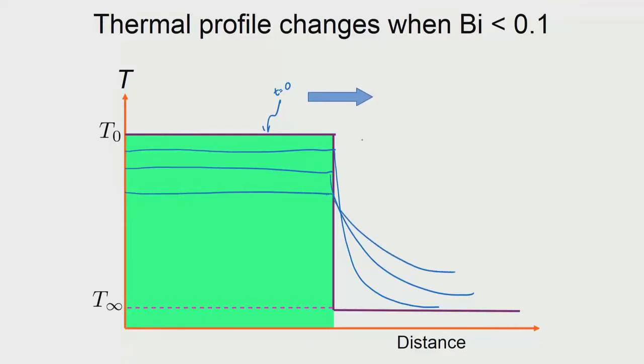So, which means that inside the bulk the temperature is dropping, T is dropping, and outside the drop in temperature is then matched with the heat that is lost, and that Q is of course given by h into T, which is the temperature inside, which is same as the surface, minus T infinity. T infinity is given. So, this makes it a little simple. So, this kind of an approach is what we are going to see to look at how the temperature